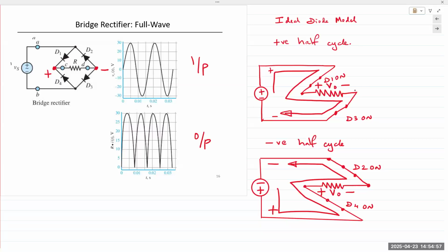Those chargers were only meant for one region: if it's 110 volts, you could only use it in North America. If it was 220 volts, you could only use it outside of North America. You could not use it in either place. Do not bring something from outside and use it here because the transformer input is fixed. Now it's not so.